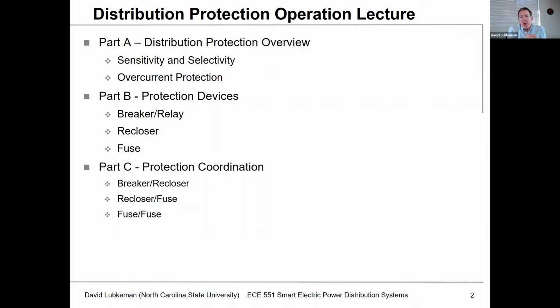And the third part, we'll get into protection coordination and talk about what has to be the relationship between the breaker and the downstream recloser, the recloser and downstream fuses, and what sort of relationship do we need to get several fuses to coordinate with each other.